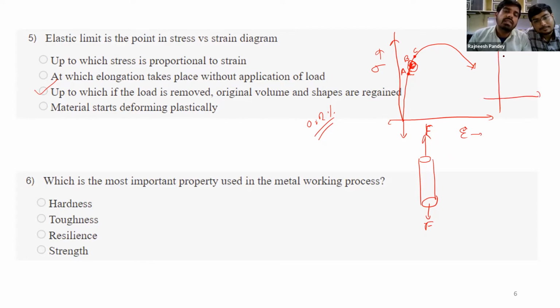But in the case of low carbon steel, you will get this kind of curve. You have seen this. Here there are two distinct points where we can define the yield point, where first plastic deformation occurs. But in the other case, we cannot get a distinct point where we can tell where first yielding starts.